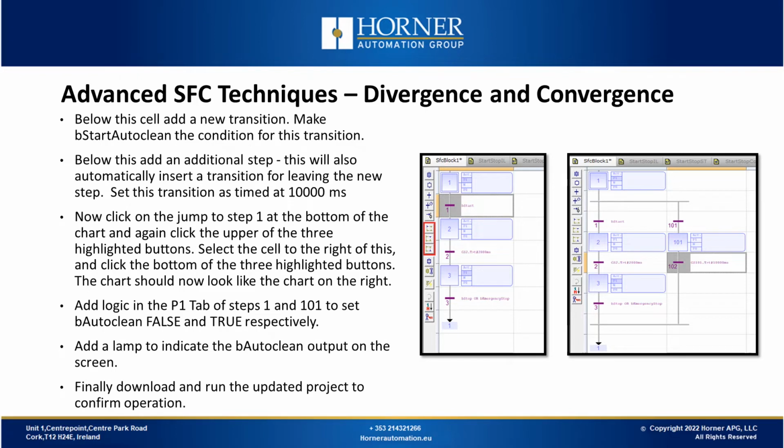Below this cell we'll add a new transition and we'll make the bStartAutoClean variable the condition for this transition. Below this we'll add an additional step.